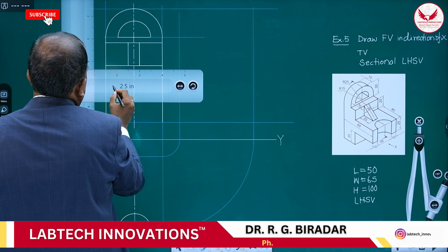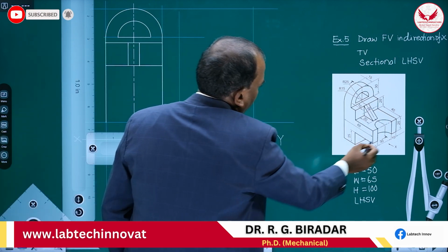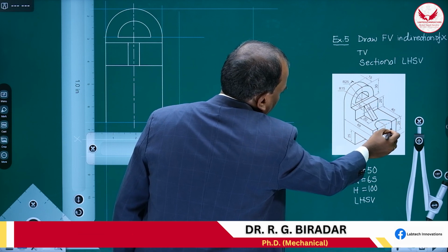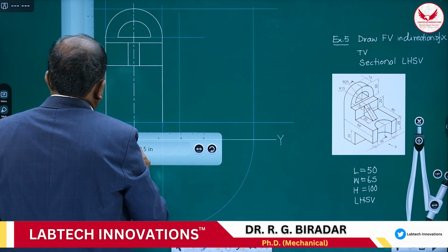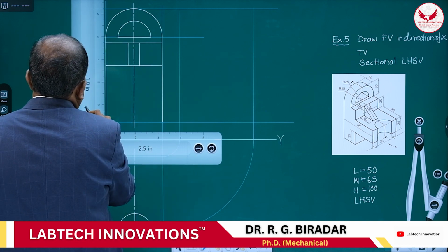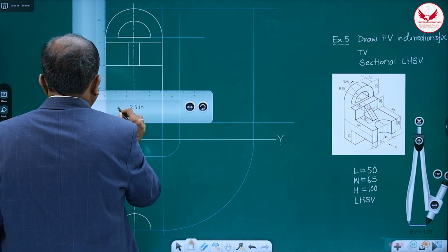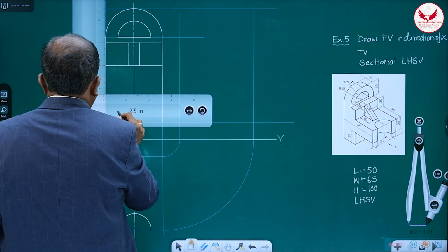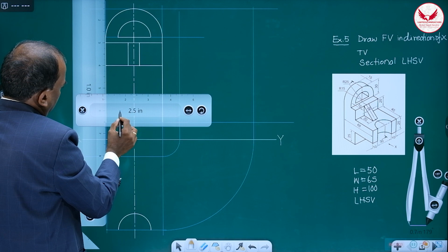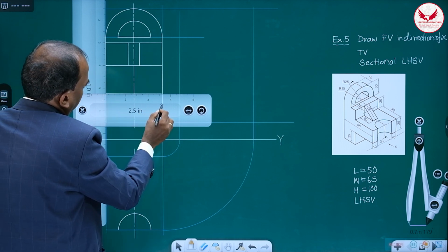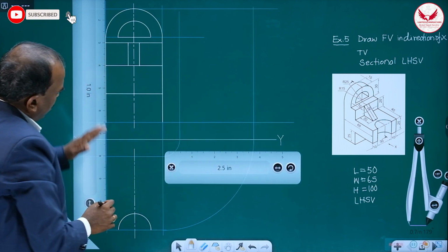On the left hand side, that rib is over, this portion is over. Then afterwards, this height is how much? It is 25. Then after 25 also, we have to mark one edge. After 25, is 10, 20, 25, this edge. And in this portion there is a semicircular slot.